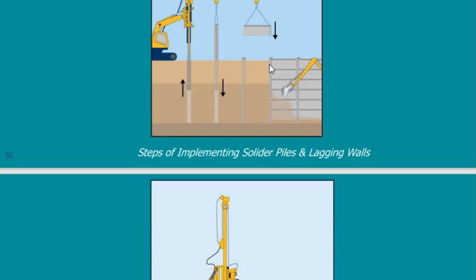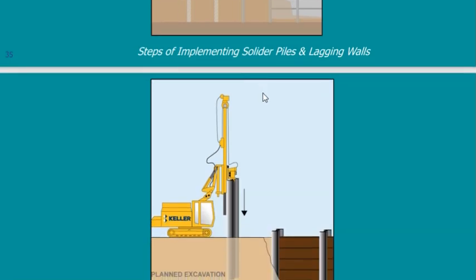Each time I put the wooden lagging, the collapse will happen once at the beginning, and then there is no other soil to collapse. So even with some soft soil, I can proceed using this. But it is better to have soil that can stay in place for a fixed length.